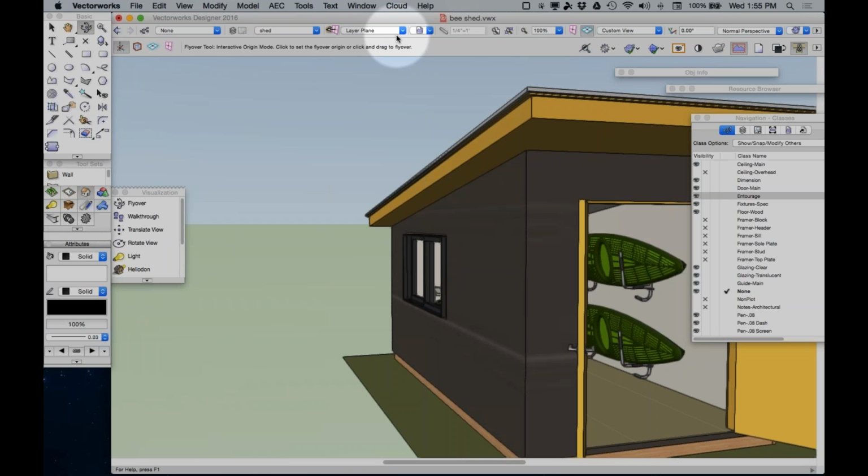I use those in conjunction all the time. The column object can be used to represent either a structural column or an architectural wrapping around the structural column, or both. And the column can be wood or concrete or steel. And if it's steel, there's a whole library of steel profiles that you can choose from.